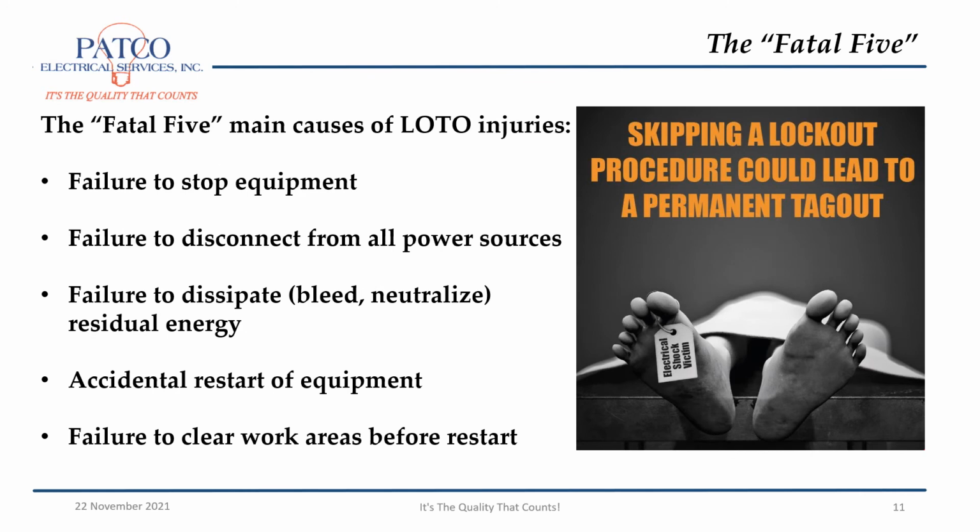The Fatal 5. The Fatal 5 is the main cause of LOTO injuries. It's failure to stop the equipment, failure to disconnect from all power sources, failure to dissipate, bleed, or neutralize residual energy, accidental restart of the equipment, failure to clear the work area before restart.